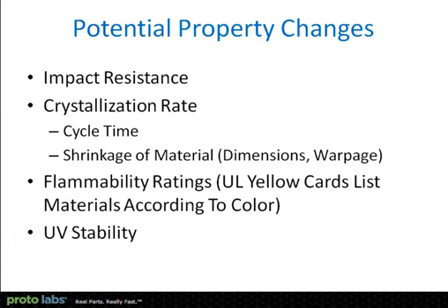However, very often you'll see it just says black, or it just says natural, or it may say natural, black, and red. And so what this basically tells us is that color is important to even things like flammability ratings, and there's a recognition that changing the color package can change this rating.